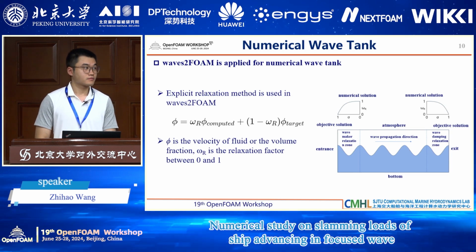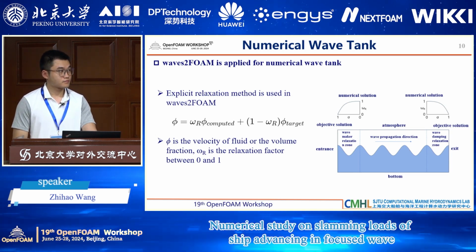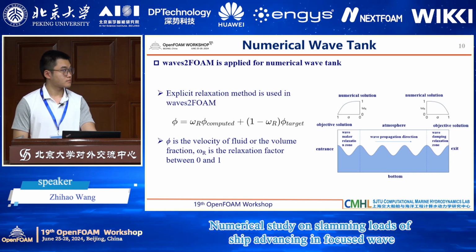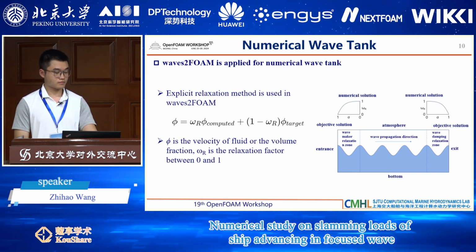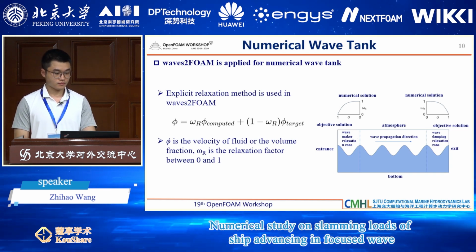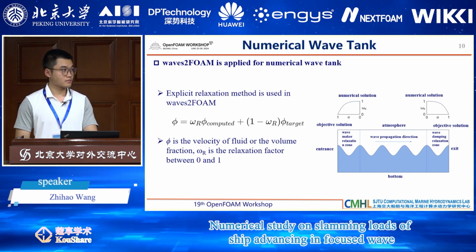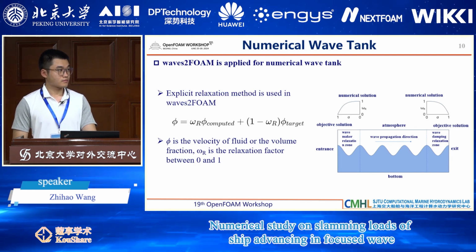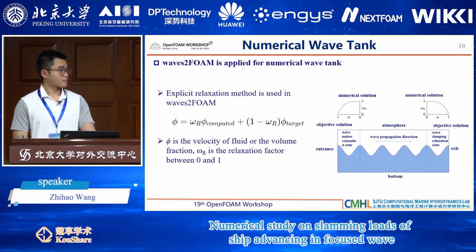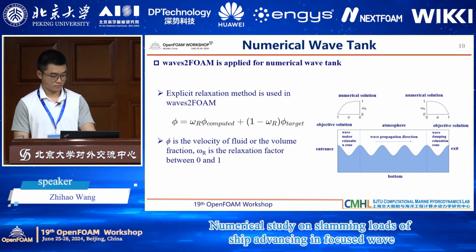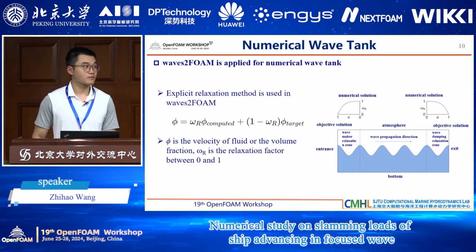It is possible to do it, and I have done it, but you have to be very careful with the motion, because the motion of the wave maker, as you probably know, needs to be very precise. And we have issues with mesh deformation, time step size, and the actual effect of the pressure. So it is possible, but the simulation would be maybe 3 or 5 times more expensive. Okay, may I ask some questions, please?